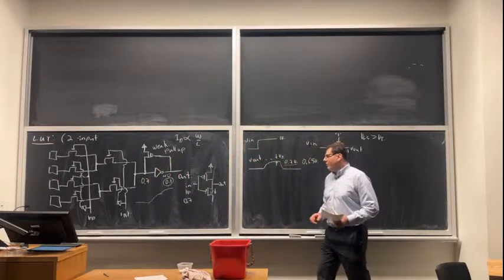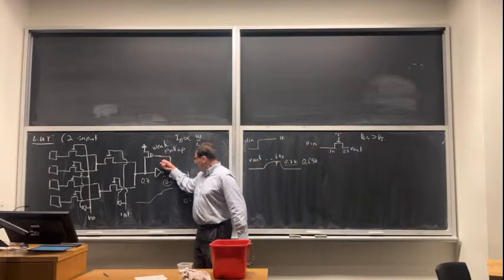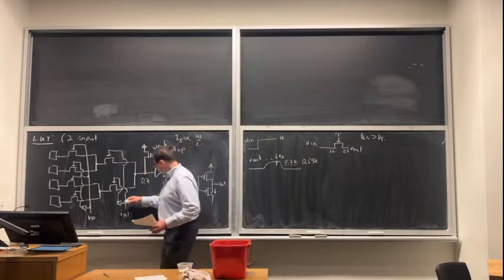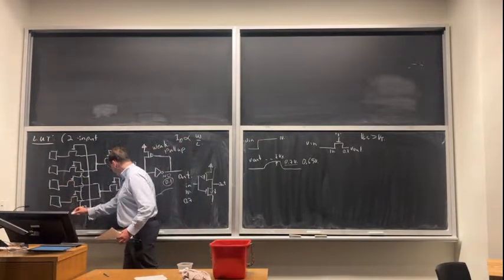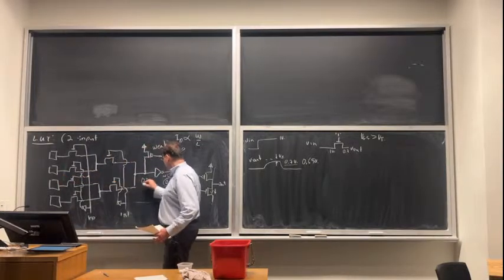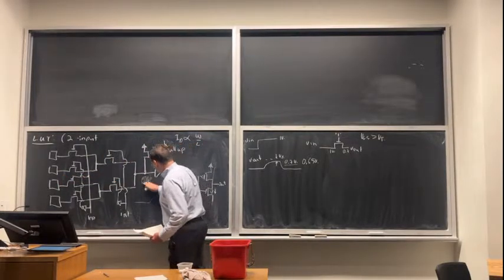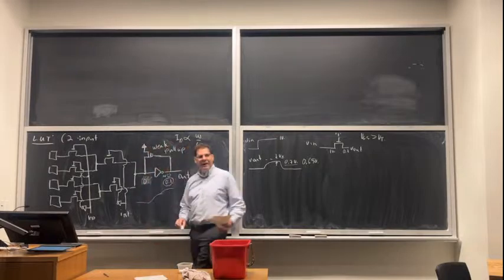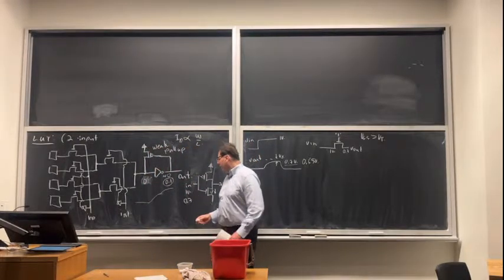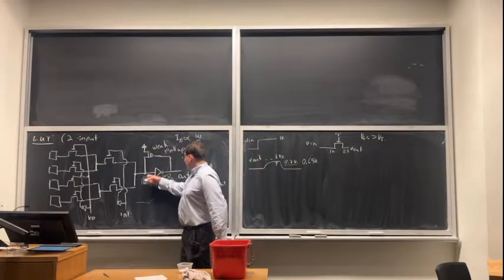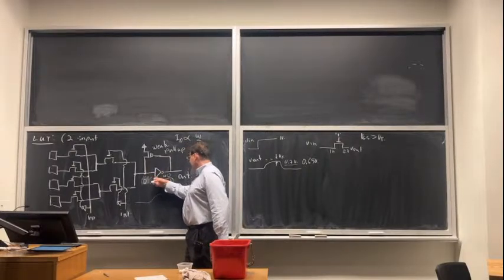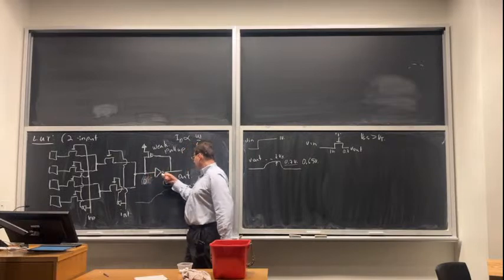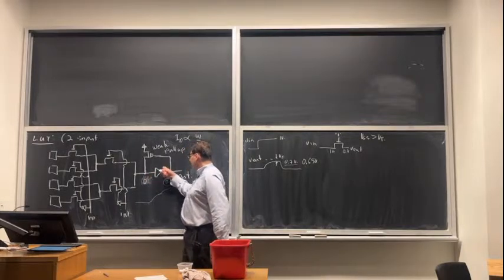You have to make this relatively weak, because when input 1 changes, and maybe you connect to a different SRAM cell, maybe this signal now goes to 0 because a new input has come in. This goes to 0, this is still trying to hold it up. If you pull it down close to 0, this will start putting out a logic 1, which will turn this off.